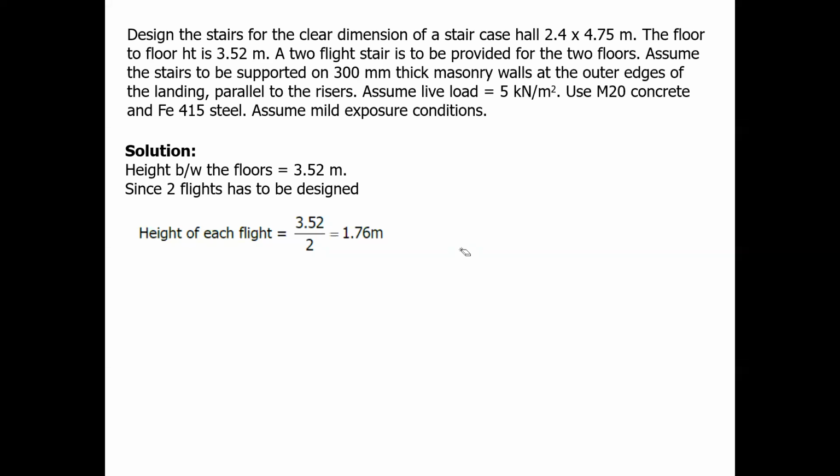Any standards? As per BIS, you have to take the riser from 130 to 170. So here I've considered 160 mm.